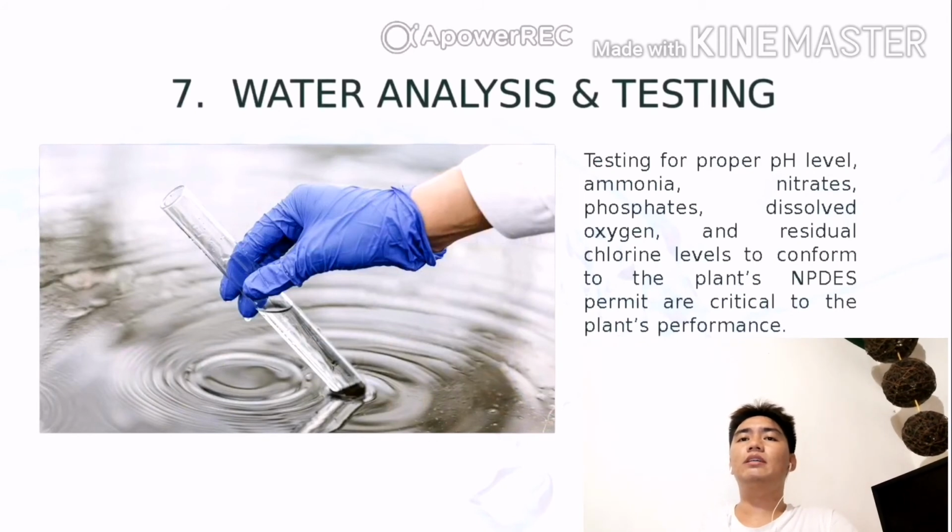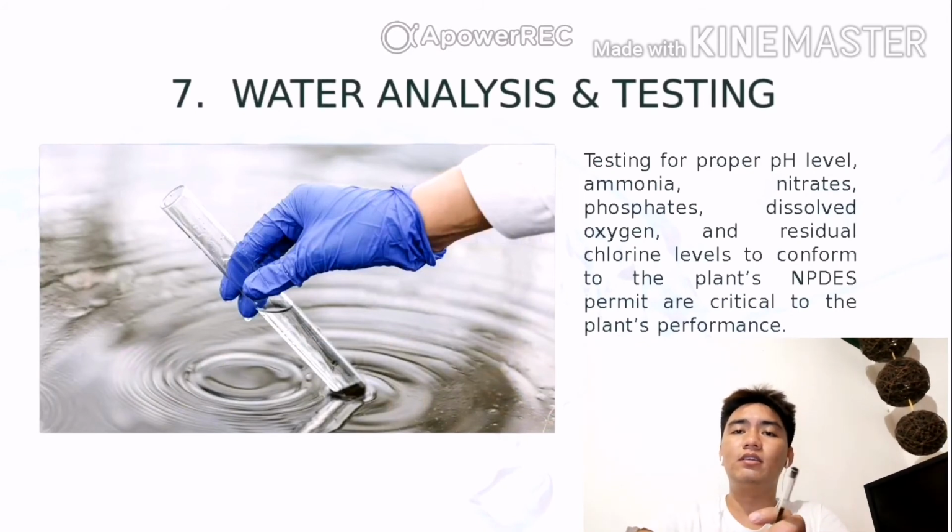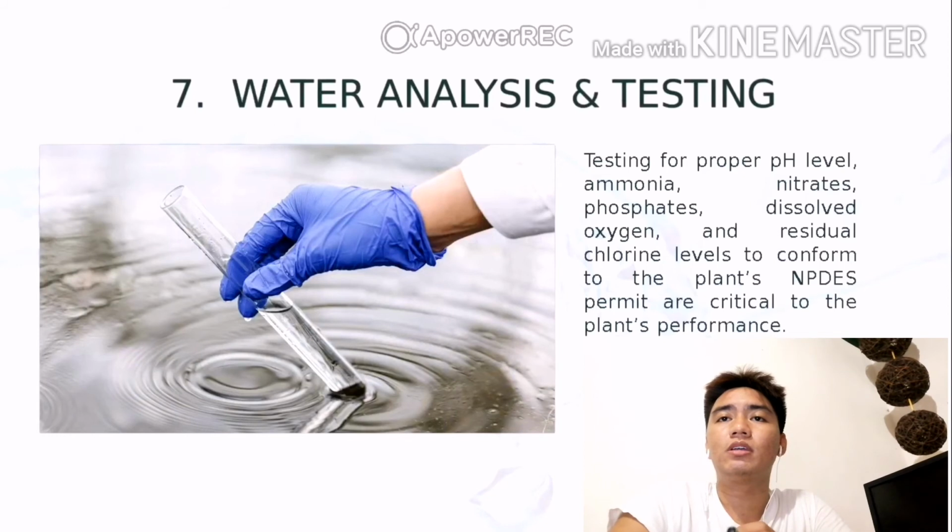Stage 7, water analysis and testing. Testing for proper pH level, ammonia, nitrates, phosphates, dissolved oxygen, and residual chlorine levels to conform to the plant's NPDES permit is critical to the plant's performance.